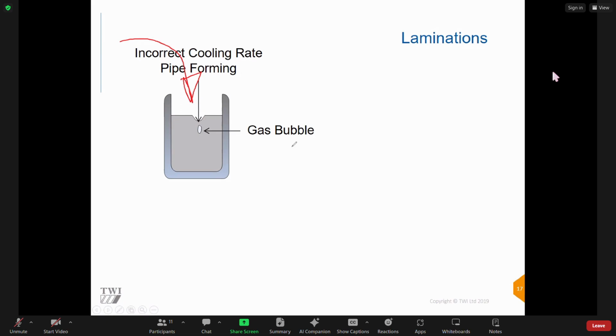so it's in a liquid form and fills in. Any low melting point impurities again are pushed into the middle, because obviously the middle's the last place to cool. And then they get pushed up to the surface. Then when this block solidifies, we get what's called a pipe. And then again, that's chopped off, and then the steel is good to go.